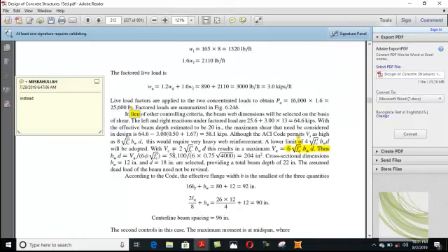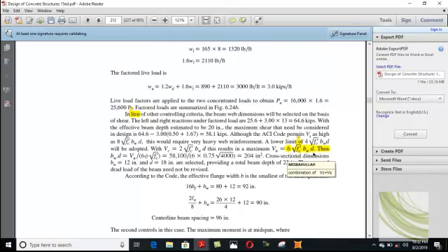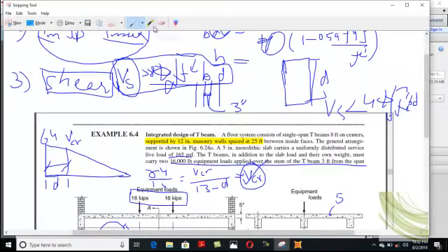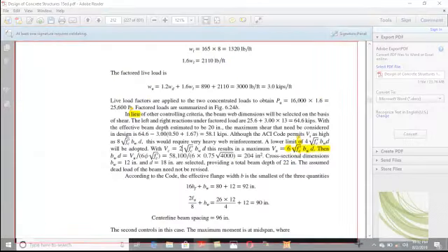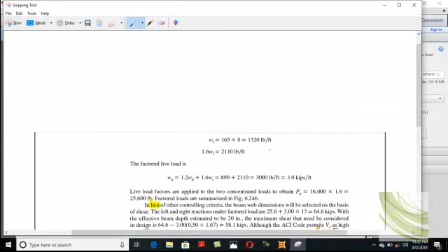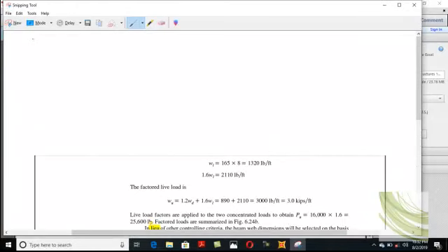We will adopt it. This is the shear capacity of the concrete. It is almost taken as 2 into square root of Fc prime into Bw into d, and Vn basically, I will clarify some points, because you people will be confused.